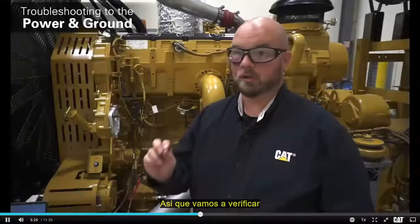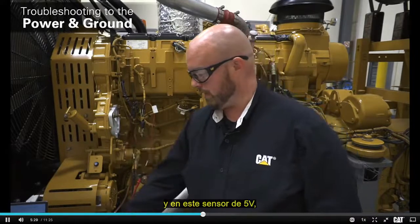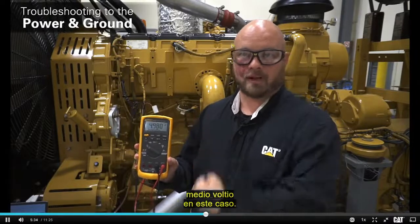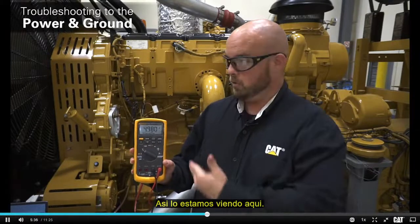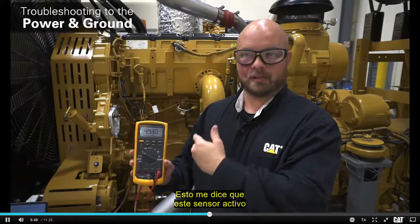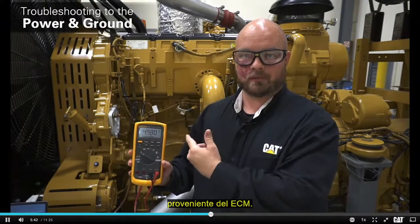We go to check for power between pin A and pin B on this 5-volt sensor. What we should see is 5 volts, plus or minus half a volt in this case. We're seeing that here. This tells me that this active sensor does have the proper voltage coming from the ECM.